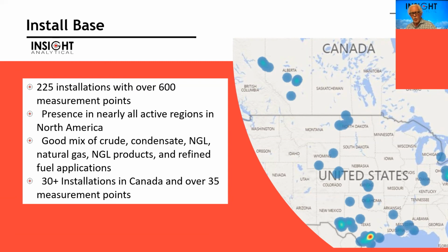We didn't talk about it here. We're going to do another one of these talks probably in a month and a half from now, and talk a little bit more about crude oil blending and about transmix, or measuring the difference between batches as things move down pipelines, because a lot of our pipelines are batched. And one of the strengths of the analyzer is it can measure different things. And so now we can tell, well, are you on spec for gasoline? Are you running condensate right now? Are you on spec for jet fuel? And so we can look at different products as they move down the pipeline.